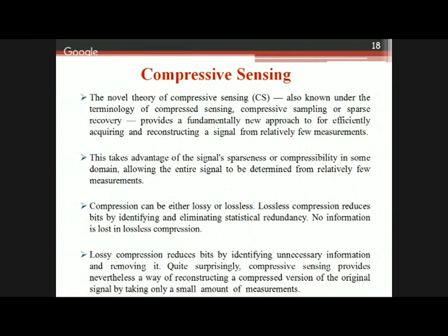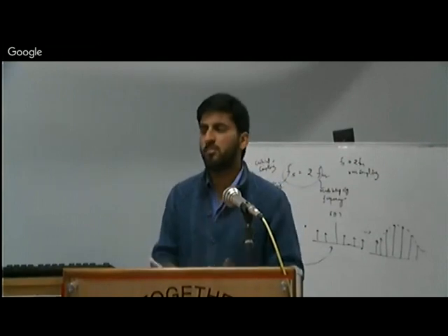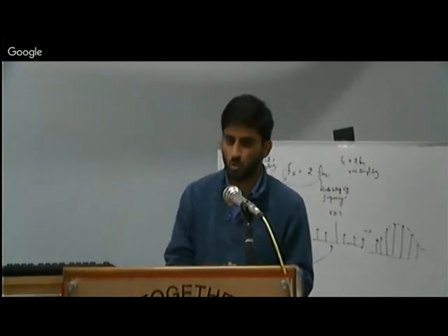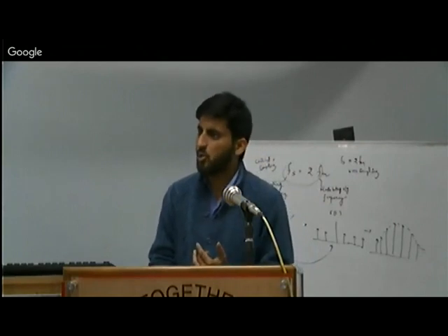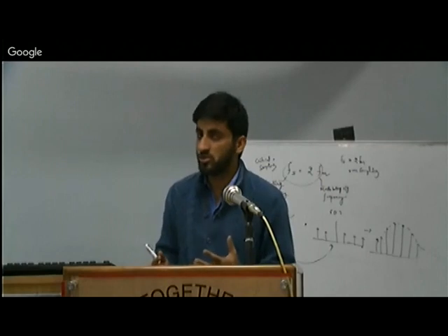Because when you pass your digital signal through the reconstruction filter, which is your low pass filter, it is going to reject all the other samples. It is going to give you the original sample, and reject all the other samples. So why are so many samples taken into account? This is going to waste our memory resources. This is going to increase our cost,